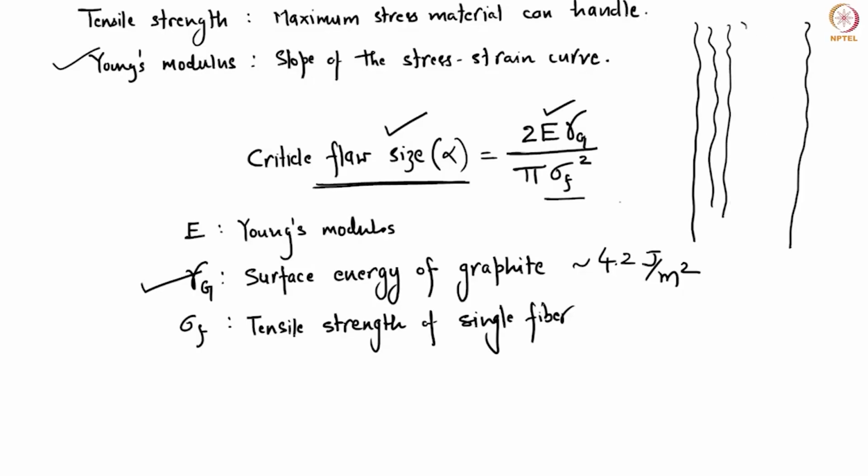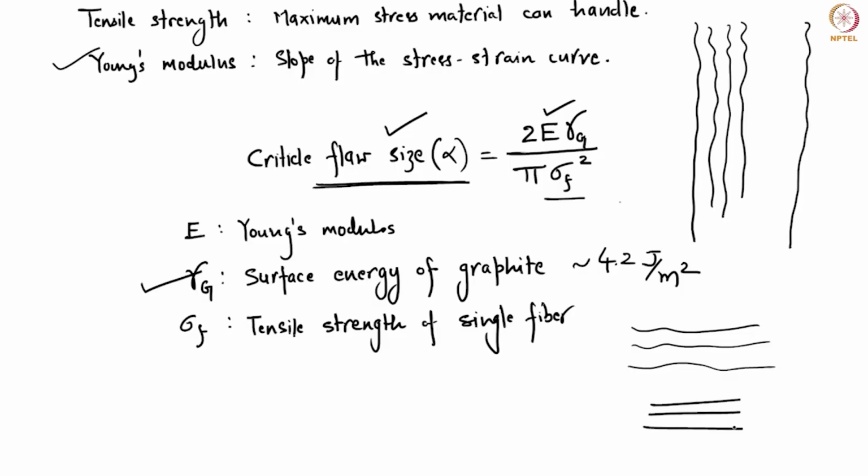Why does that happen? In the beginning, when you've heated your carbon polymer fibers to about 1000 degrees, what you have is these turbostratic carbon sheets. What are turbostratic carbon sheets again? These sheets are also graphene-like, but they contain several defects, and therefore they are not organized in an ABA fashion, as in the case of graphite.